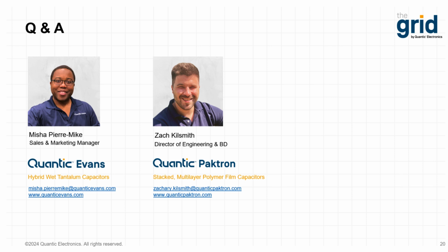As I discussed previously, tantalum capacitors are a bit more energy dense. They pack more capacitance per unit of volume. So if volumetric space is a critical constraint, tantalum capacitors would really be the way to go, because an aluminum electrolytic capacitor with comparable electrical characteristics to its tantalum counterpart is going to be physically larger. So again, I always start by asking, what does the application need? And once you understand what the application needs from a volumetric space standpoint, from a reliability standpoint, from a cost standpoint, then you can back into which capacitor technology would be the right one for you.